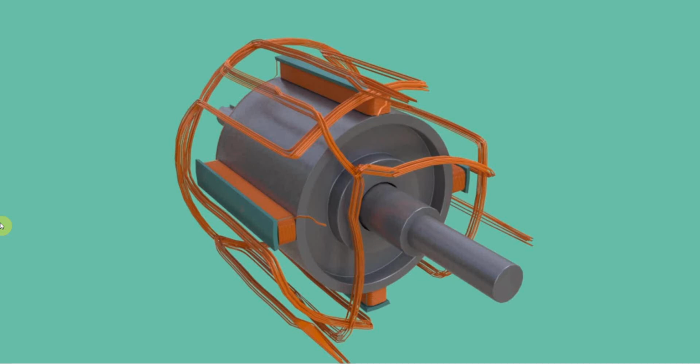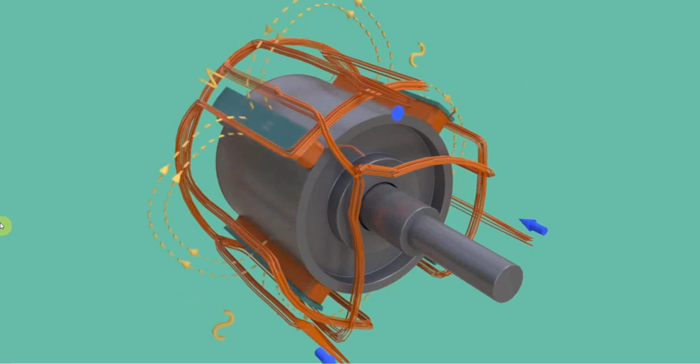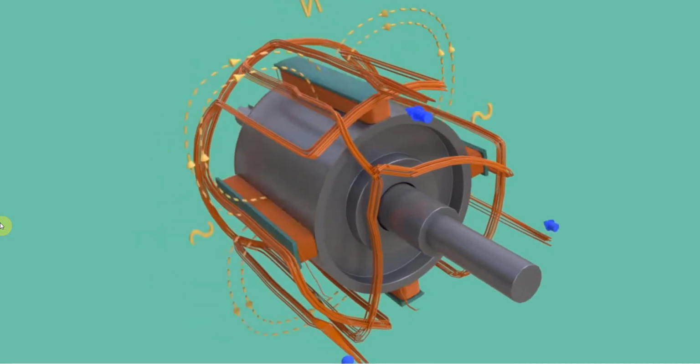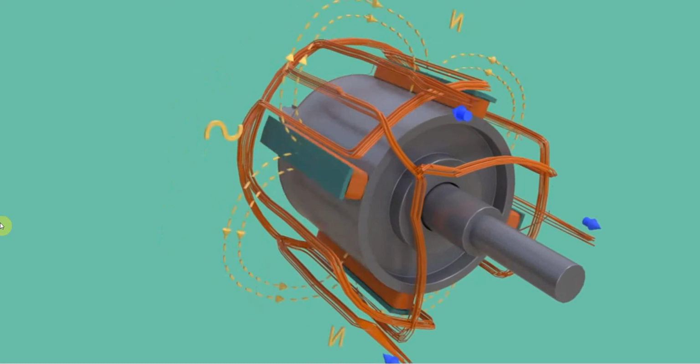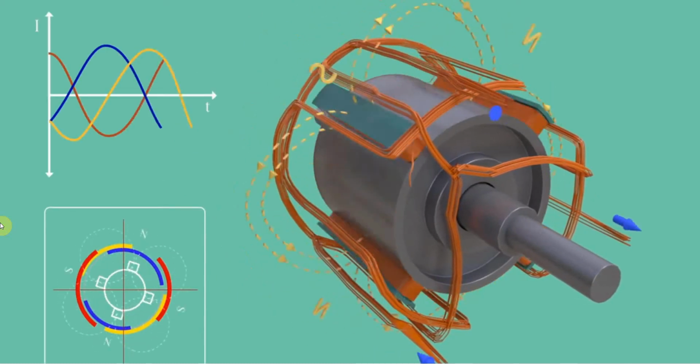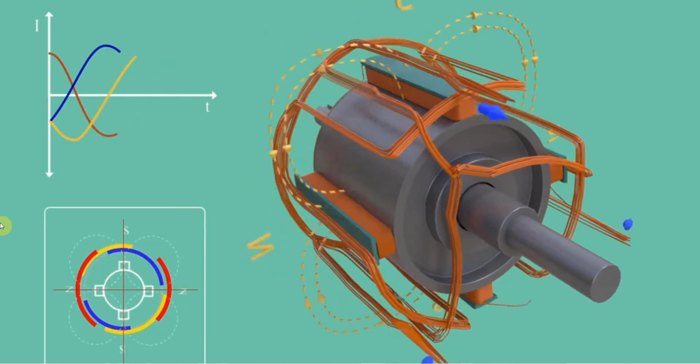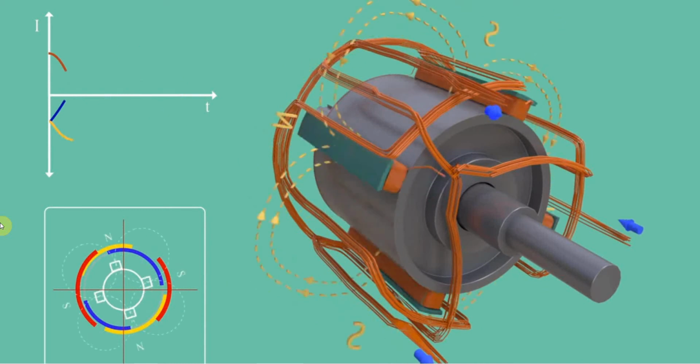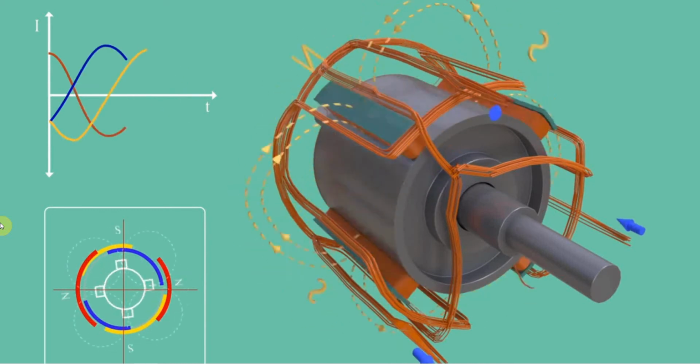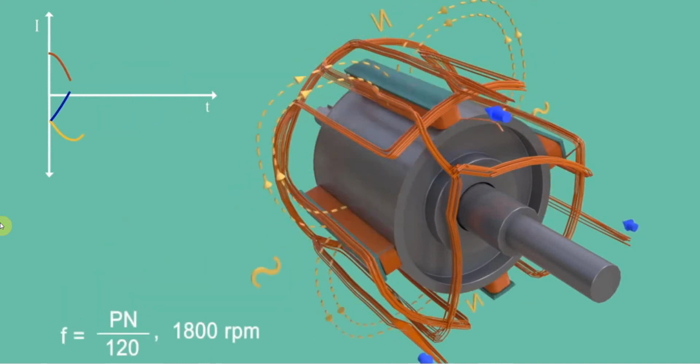Generally one end of these 3 coils are star connected and 3-phase electricity is drawn from the other ends. Neutral cable can be drawn from the star connected end. It is clear from past equation that in order to produce 60 Hz electricity, a 4-pole rotor should run at the following speed of 1800 RPM.